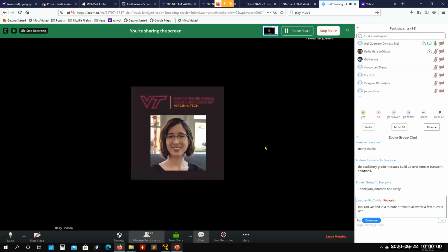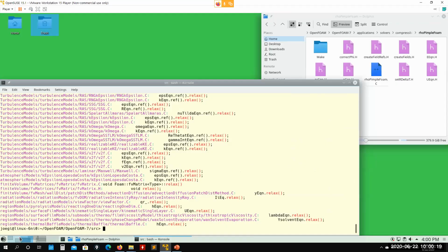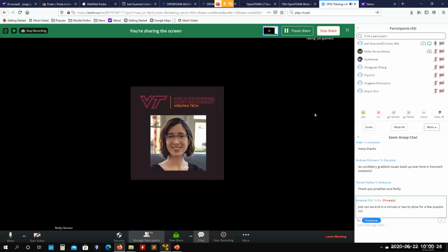Yes. You should be careful of that. Yeah, that can happen. And actually, in the airfoil case, the one I just ran, if you don't use the slope limiter, the gradient limiter, that oscillation will accumulate. And actually, you will see in this solution, I don't have it, but you will see an expansion artifact in the upper surface of the airfoil. So just play with that case and switch off the gradient limiters, and you will see those oscillations in the upper surface. And then immediately when you enable the gradient limiters, it will go away.